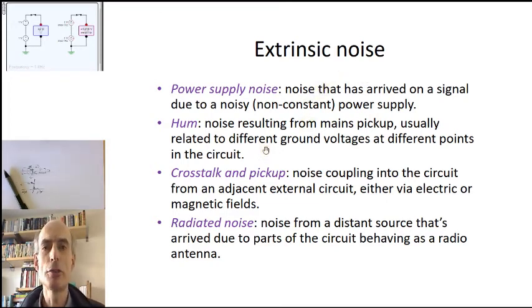Hum, often related to mains pickup, usually a problem to do with insufficient grounding or not enough attention paid to get very low impedance ground paths in a circuit, can result in characteristic 50 Hz waveforms in a circuit as well.